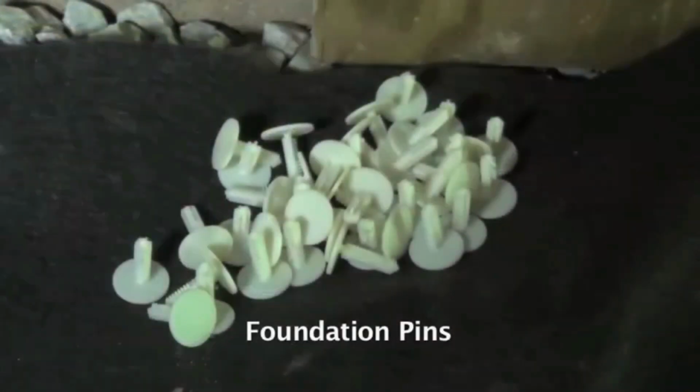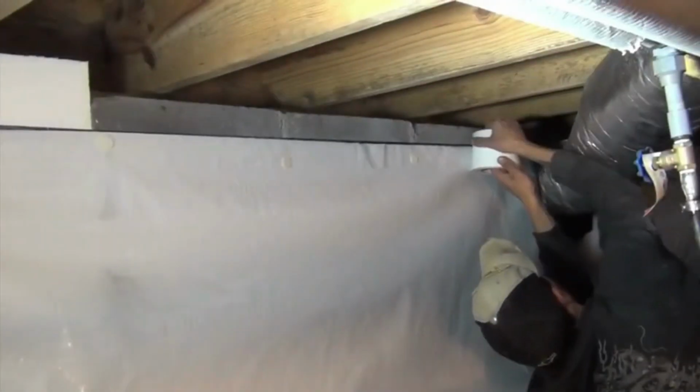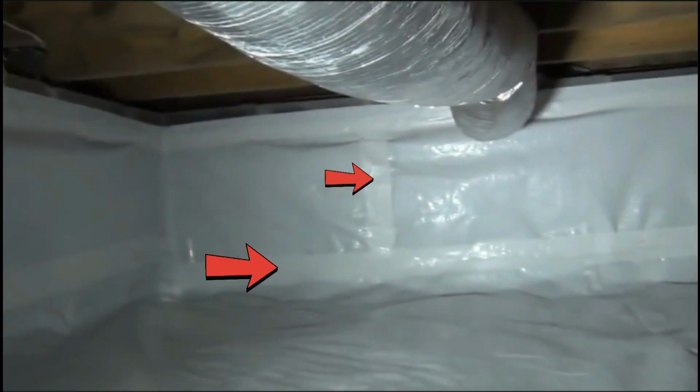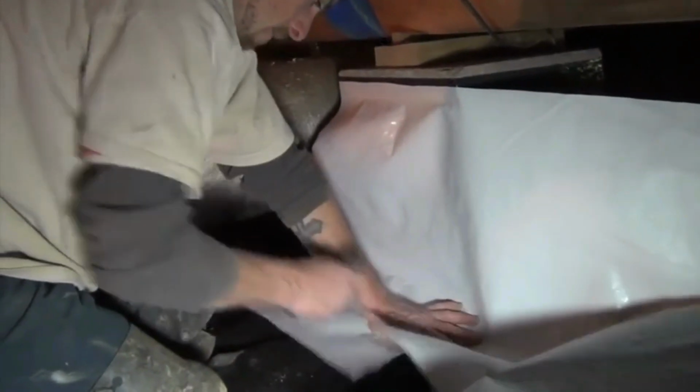We then add our foundation pins into the tape line area as shown here. This helps to support the vapor barrier in the future. We finish the walls off by adding a line of our seaming tape over top. Then, we lay the vapor barrier down on the floor and seam it up as you can see here, using the seaming tape. This same process will be completed around the piers.